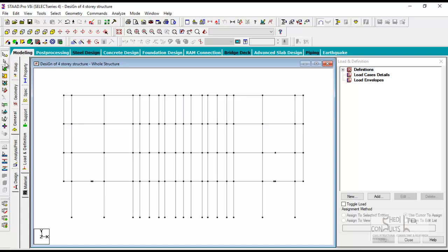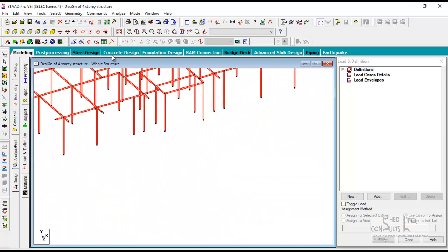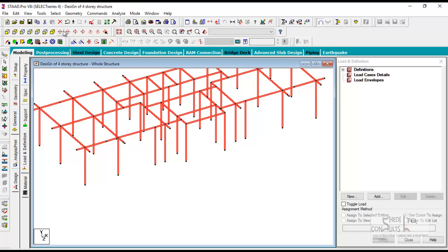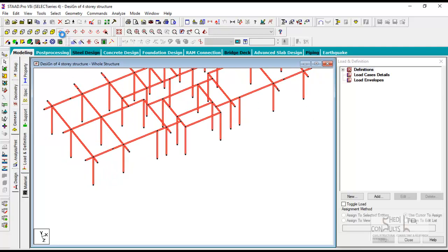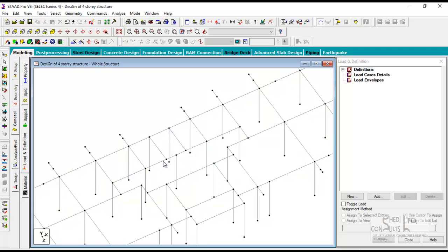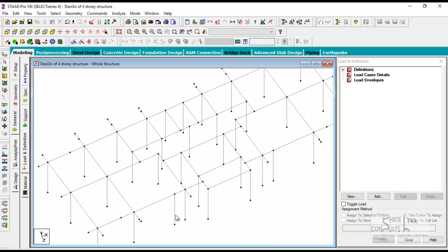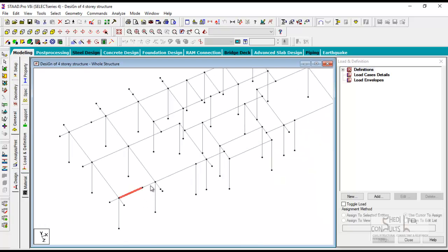Front view. Select the entire first floor and the columns, view selected object only, and like that. So what am I seeing there? Okay, so the column does not exist here, so the first floor is largely correct. But I can see that this beam is broken here into two, which is wrong. I need to merge it as one beam.